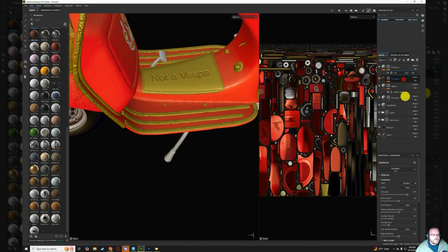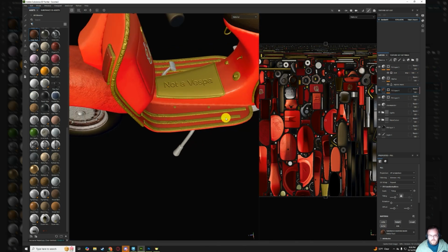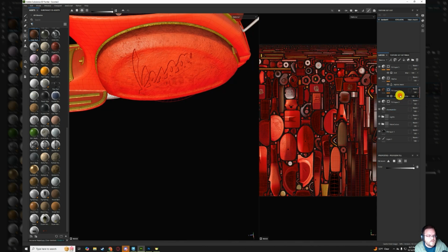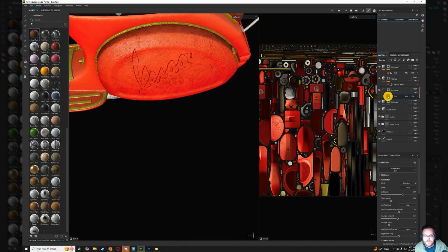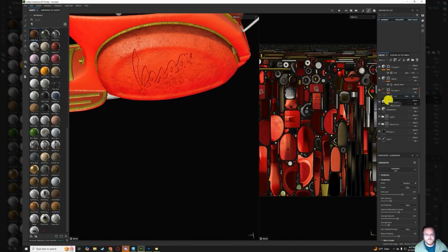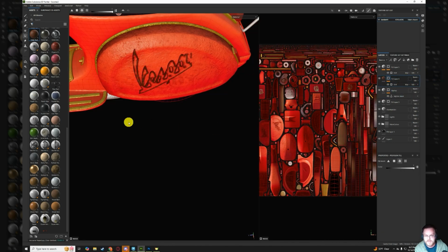this is another kind of important part, I think. If you have your fill layer that is attached to the anchor, I believe this is the right one. Yeah, it's attached to the anchor, and that is below your anchor point on your layer panel, then it will not actually affect that layer. It has to be above it. The anchor point has to be below everything that wants to affect it. Important point.